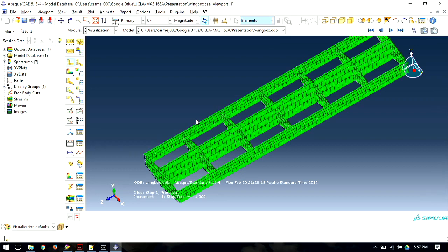So based on your bending moment and your torsion, that'll dictate usually what percentage of 0s and 45s your skin is going to have. Because torsion, your 45s and minus 45s take that load, whereas your bending is your 0s. So usually you have a low percentage of 90s in there, because 90s would be the fibers running this way, but no load is really running in that direction. It's shear, which produces tension this way, compression this way, either way you look at it. Those are the 45-degree fibers, and your 0s running this way are taking the bending loads. So it has its advantages with that. That's why you typically see composite skins and metallic substructure.